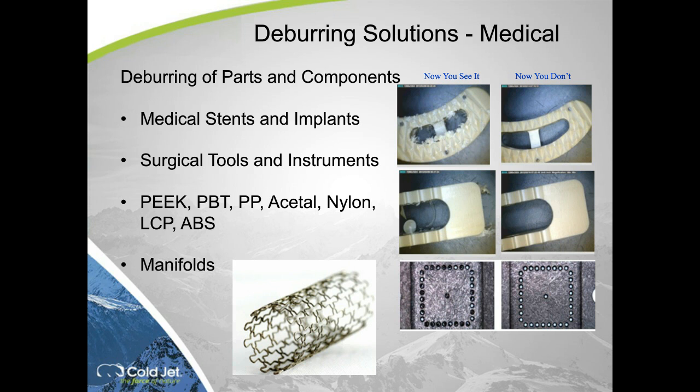The lower left is actually not plastic. That's a nitinol stent, which is deburred using the microparticles. The 3 millimeter pellets would damage that type of device very quickly. That's where the microparticles come into play.